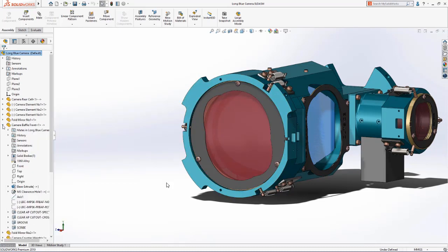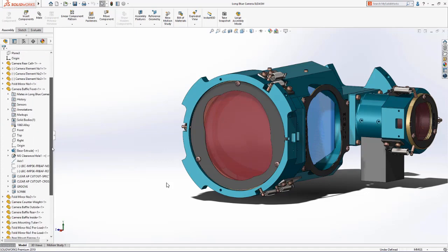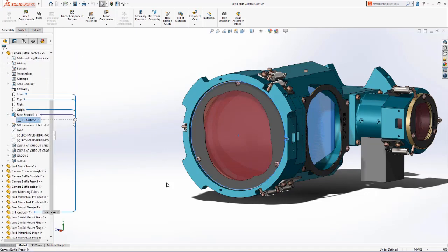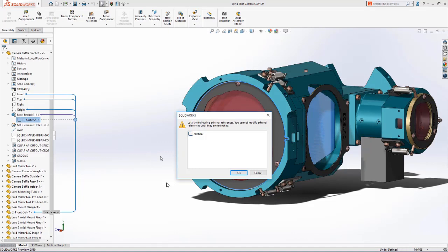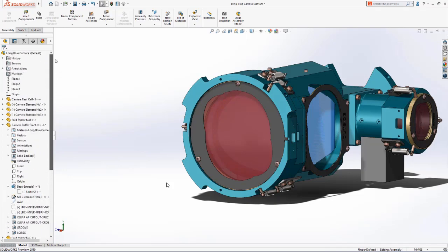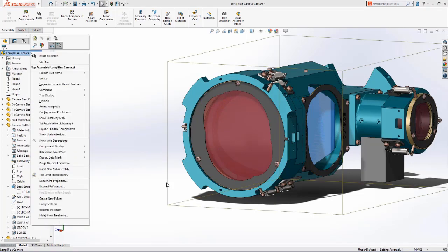Building relationships between features and parts is a powerful method of capturing design intent. SOLIDWORKS 2019 makes it even easier to view and manage external references. References can now be broken or locked when dynamically viewing parent-child relations from the FeatureManager. When using a top-down approach to design, assemblies can consist of many parts, each containing numerous external references.